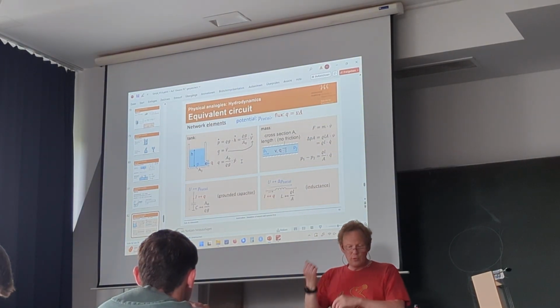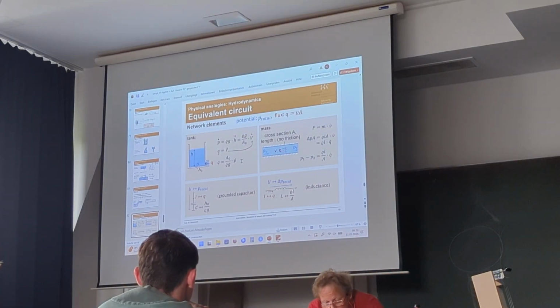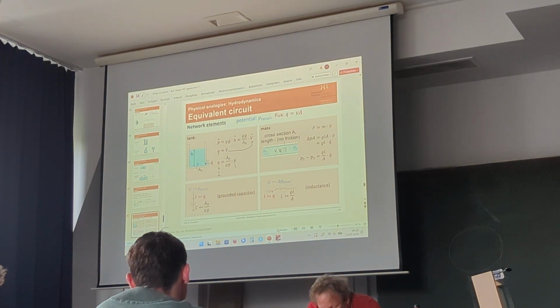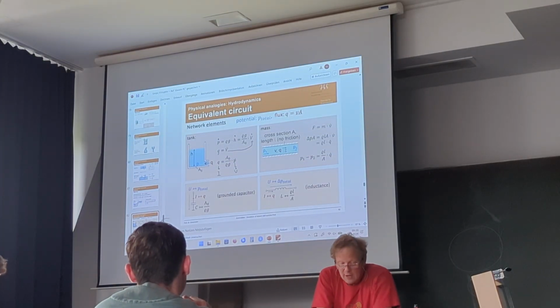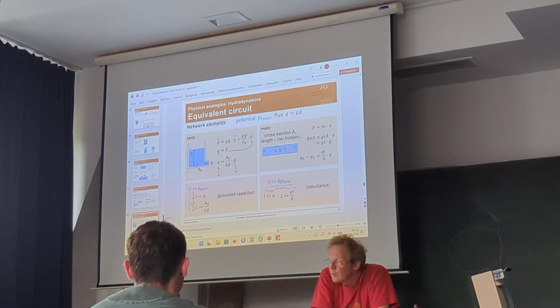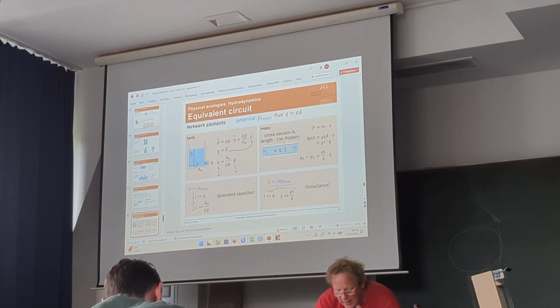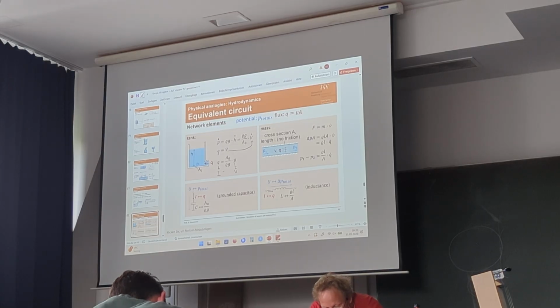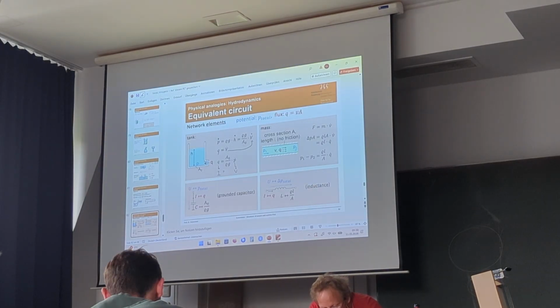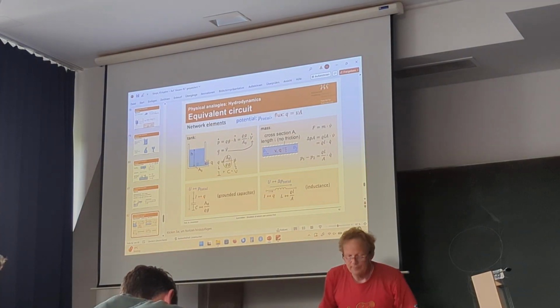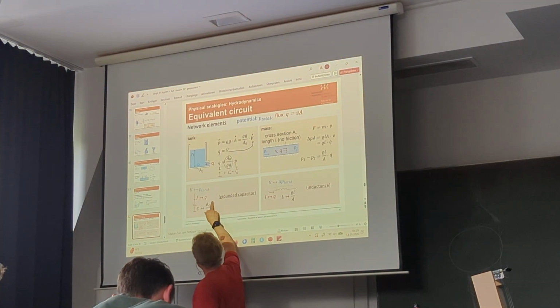This is somewhat similar to electric things. If the volume flux has to do with current, and the pressure has to do with the voltage, but it's the derivative, so we have the derivative of a voltage here, then this is similar to an electrical capacitor. In the equation, we have the capacity here, and that's where this term comes from.